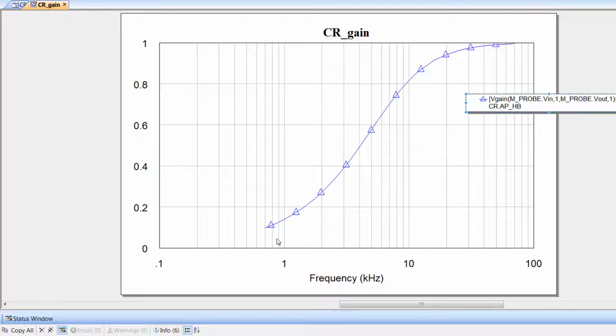Now you can see that this looks a lot more obvious in terms of the effect that it creates, and that is indeed a high-pass filter. Also, you can now see what I meant by a logarithmic scale and a decade. A decade is basically a difference of a power of 10. So we go from 1 to 10, from 10 to 100, etc. And within each decade, normally in the lab, you only measure where there is a vertical line. So you only measure about 10 points per decade. This is how a frequency response is normally worked out.